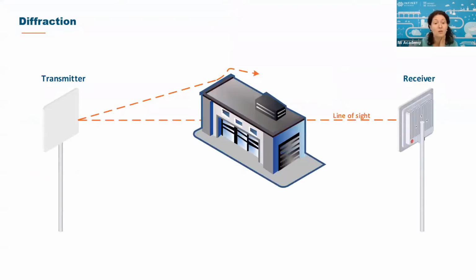The Fresnel zone between the receiver and the transmitter is blocked by the building. However, the radio signal from the transmitter goes around the corner of the building, changes direction, and reaches the receiver. Please note that the signal's energy will be scattered into the medium because of diffraction, leading to a decrease of the maximum distance compared to the line of sight conditions.